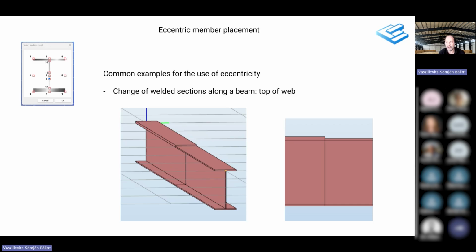And again, our principle number one with Consteel is: please always try to use realistic models. If you make models which have such sort of shifts, not every result will be accurate. And of course, Consteel cannot correct it. Consteel doesn't know that the structure in reality doesn't look like this. Consteel will just blindly follow everything that is given and will maybe do calculations with inaccurate results.